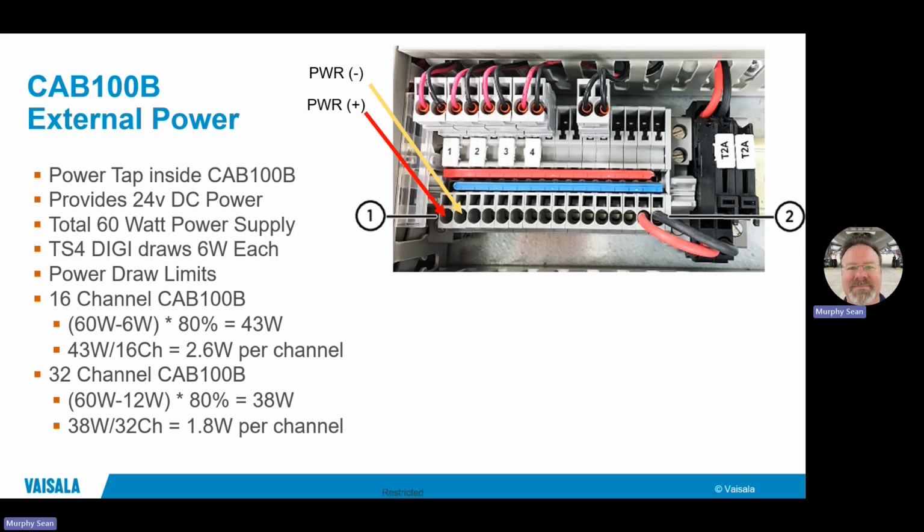You just bring your positive and negative power leads and connect right where I'm indicating on there, or any one of the pairs that are along that lower rail. You'll notice up above where it says 1, 2, 3, and 4, those are the power connectors that actually go to the loop powered injectors for each one of the data loggers that are in there, the power 4 to 20 milliamp. So those would not actually be installed if you were using this for external power, because you wouldn't be wiring the transmitter 4 to 20 milliamp. And I'll get into that in a few minutes.